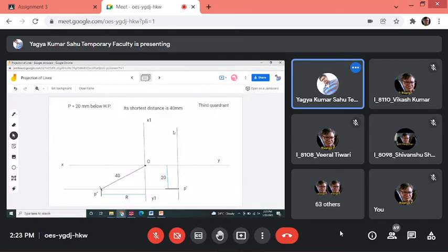So in this projector line, at a distance of R, you will get small p, the top view. Yes or no? Starting from this particular origin, draw another point p at a distance of R, which you can easily measure with the help of your normal scale.